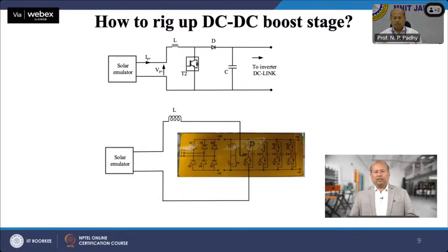For our application, we are using only 3 legs because we are demonstrating solar generation for balanced 3-phase 3-wire system. Moreover, we are talking about only the single stage conversion. It is also possible to use the same setup for 2-stage conversion as well. The leftover 4th leg can be used to build the DC-DC boost stage. And how can we do that? Let us understand in detail.